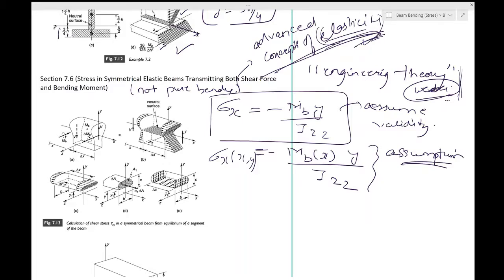However, you are only getting the stress field using this approximation assumption. You are not ensuring geometric compatibility, you are not ensuring that the stress and the strain relationships are there. So there is no guarantee that your answers are correct. You are only doing one step out of those two.